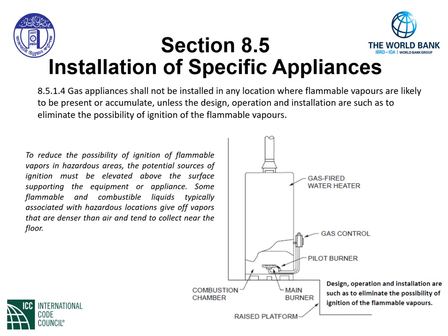Some flammable and combustible liquids typically associated with hazardous locations, of course, give off vapors that are denser than air, and they tend to collect near the floor. So, designers, engineers, installers, inspectors, we all have to be aware of this, and we need to make sure that the appliances, number one, designed by the engineers, are specified at elevations and areas that do not permit readily ignition of flammable vapors that may be present in certain environments within our buildings.